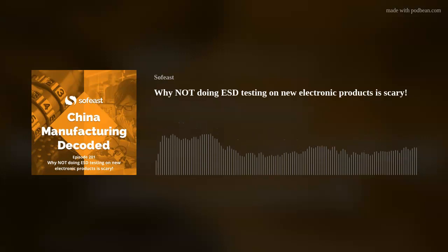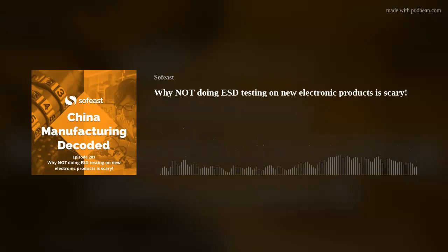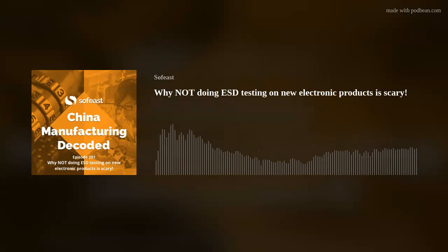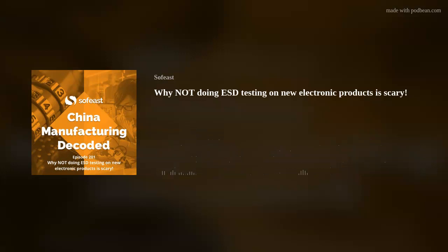One of the advantages of this type of testing is that it represents a fast and efficient way of knowing if ESD is actually going to hurt the equipment. And it's highly relevant to scenarios involving automated handling and packaging processes. You know how sometimes packages involve plastics and paper and humidity, and these things actually do cause ESD. So generally speaking, these three types are worldwide known, and depending on different types of products and different kinds of industry, you have different levels of voltages that you need to test for.